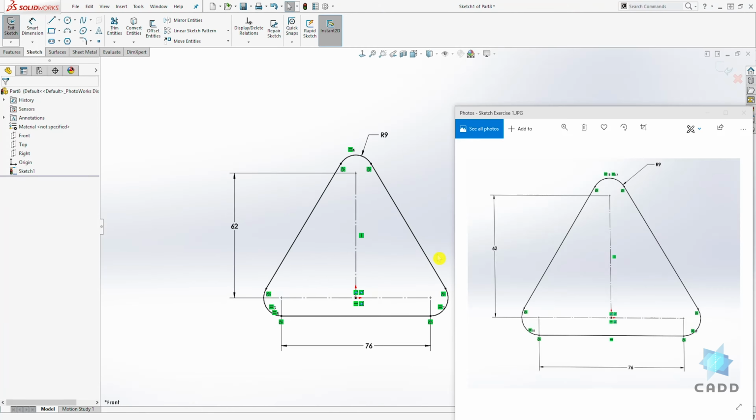And I'm going to switch this. For the second one, we'll change our units to millimeter. So go to units and click OK. And let's draw this on the top plane. So I'm going to move my plane over here so you can see it.